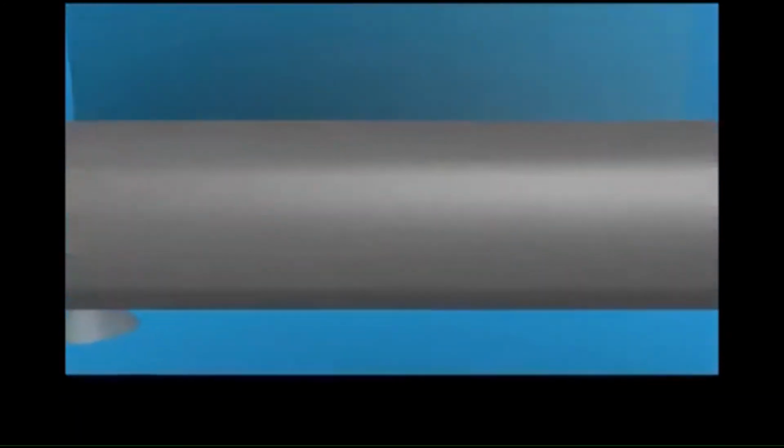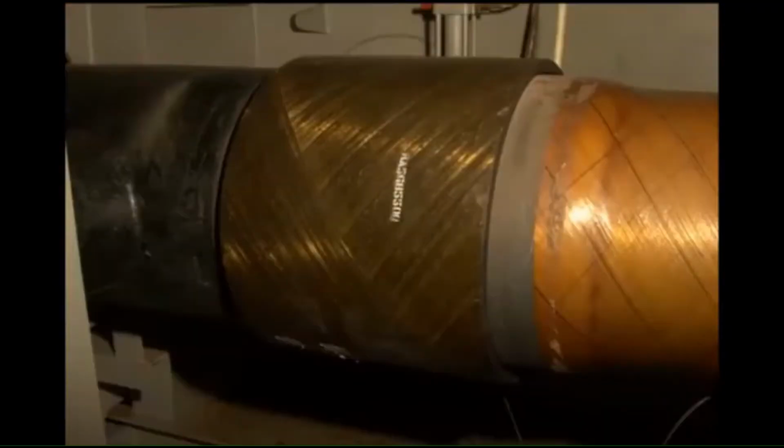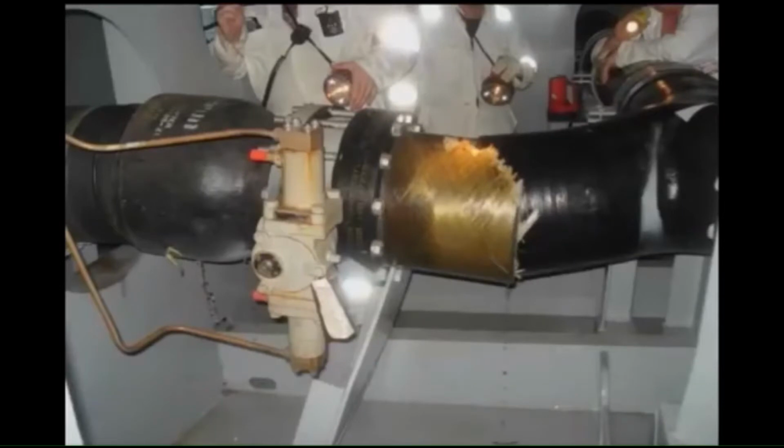Shown here is a pipeline laid on the ship's bottom, through which seawater flows for ballast filling or discharging. Joints that connect the pipes are called dressers. There are cases where dressers are damaged. This is an example of a water leakage accident due to dresser breakage caused by abrupt valve operation.